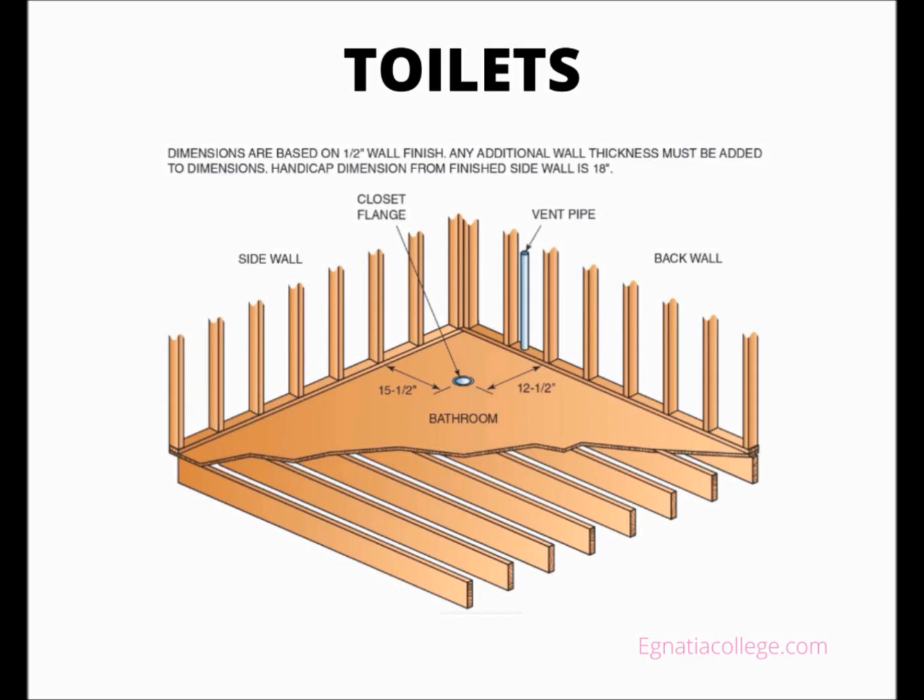The rough-in dimension is indicated when ordering by using the term rough. If a plumber does not specify a rough-in dimension, it is assumed that the drain is 12 inches from the finished back wall. Because rough-in occurs before the finished walls are installed, a plumber must know the thickness of the wall finish. Codes dictate that the center of the drain serving a toilet must be a minimum of 15 inches from a side wall or the side of another fixture for non-handicap installations.